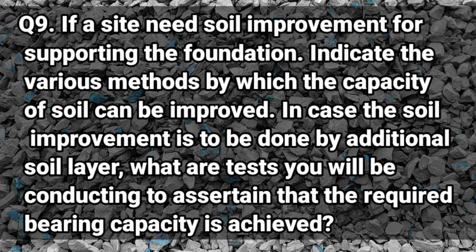If a site needs soil improvement for supporting the foundation, indicate the various methods by which the capacity of soil can be improved. In case the soil improvement is to be done by additional soil layer, what are tests you will be conducting to ascertain that the required bearing capacity is achieved?